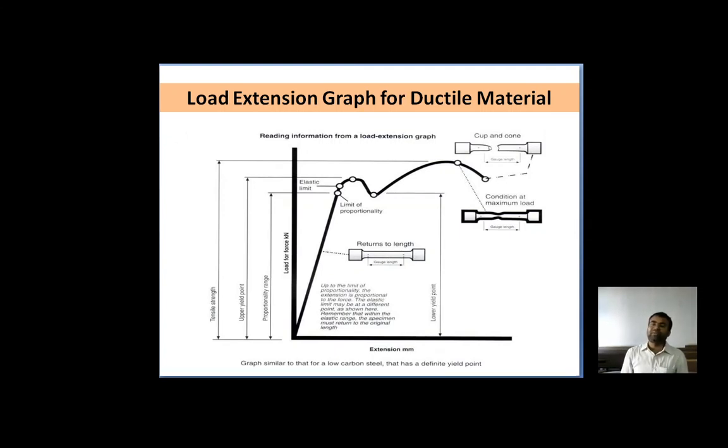So yield strength is often defined as the initial maximum stress, or else the subsequent lower yield strength is used to describe the yielding. This is because the measurement of the initial maximum or upper yield strength is extremely sensitive to how axially the load is applied during the tensile test. So in some laboratories the minimum is used, whereas in others the mean stress during the discontinuous yielding is used. The tensile strength, that is the ultimate strength, is defined as the highest value of the engineering stress up to maximum load. The deformation should be uniform along the gauge section.